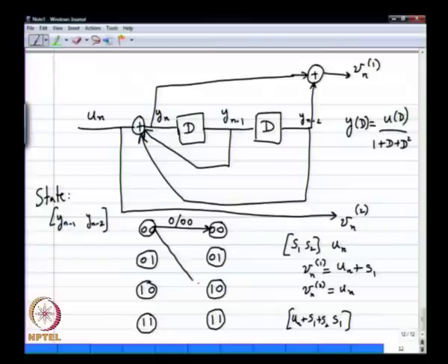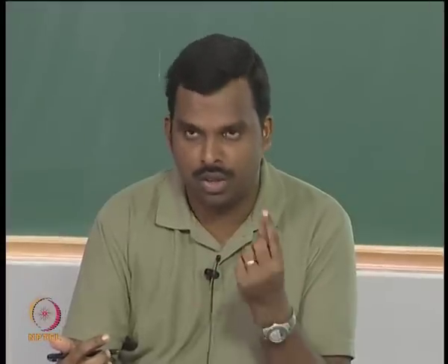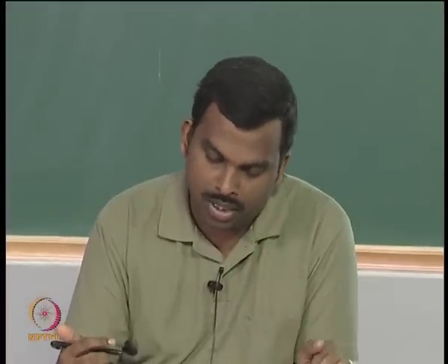Next state goes to 1 0, my output becomes 1 1. Okay, so in general, if you design your convolutional code reasonably well, then the two branches that deviate out must be separated by 2 Hamming distance, right? So you want to maximize your Hamming distance there. So when you get a 1, you should get at least 2. Okay, that is one thing to keep in mind.